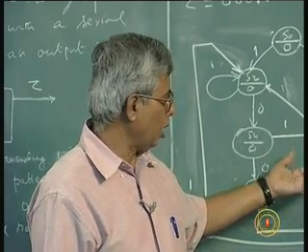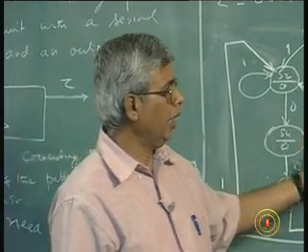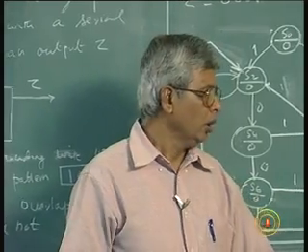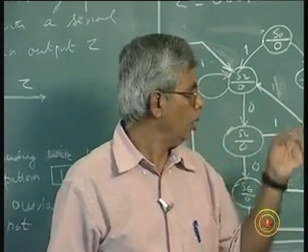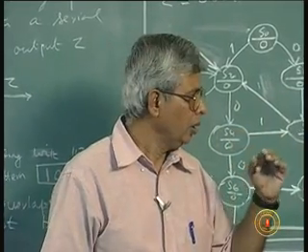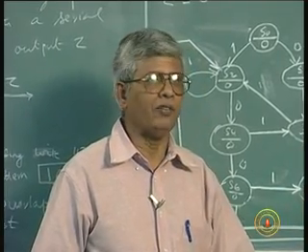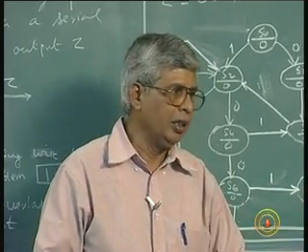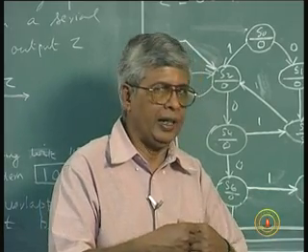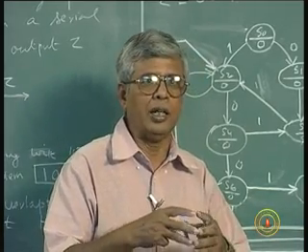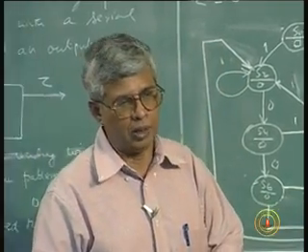Complete the state graph from here, and using these flip flops, get the Karnaugh maps for the next state variables as well as the output, and then draw the logic diagram of this. With this, we will complete the state graph drawing as an exercise, but of course, we will visit this area again. When you do the system design, naturally state graph will become part of the system design.